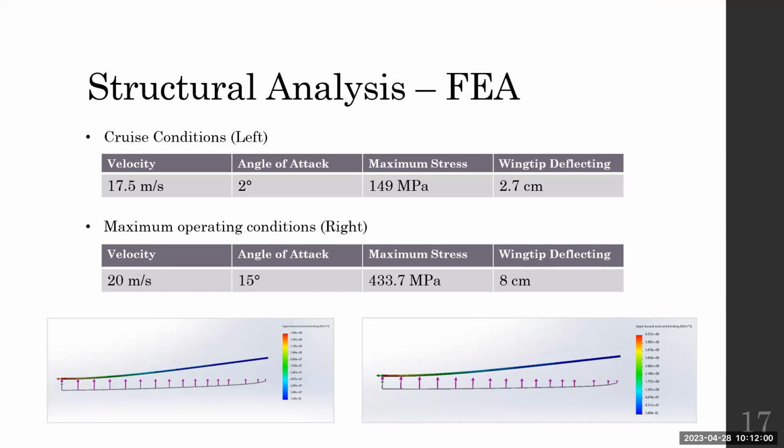Okay. Yeah, I would just be skeptical about those hand calcs, because hand calcs for a carbon fiber material, which is anisotropic, may not necessarily be accurate. The FEA is a good way to confirm that, but only if you set up your FEA properly. So how did you set up this FEA? How did you define the material properties?